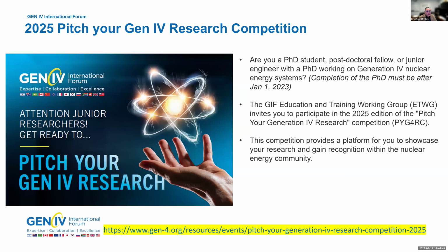Yes, it would be. I mean, the efficiency of that cycle will be much higher. And indeed, the PBMR company in South Africa way back did look at a direct Brayton. The problem there was technological challenges like magnetic bearings, or how the seals perform at high outlet temperatures of maybe 900 C. So it wasn't really a question of can you do it? It can be done. But having a direct turbine of that size was problematic at that point. The cost is maybe a bit high.